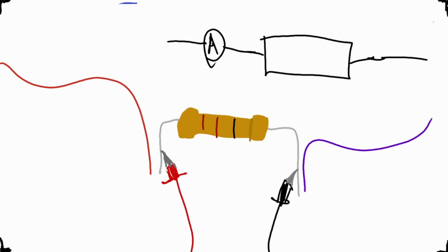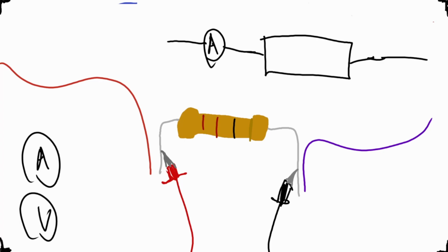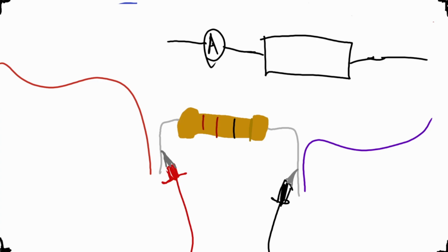Also, when I use the symbol A for ammeter and V for voltmeter, these are circuit symbols for talking about measuring the voltage and the amperage in a circuit. In actuality, it is the same multimeter. It's not like they're different components. It's just that when you're measuring voltage, your multimeter's dial will be selected towards the voltage section, and when you're measuring current, you change the dial so that it's on the appropriate current section. That's all it means in actual physical terms of using the multimeter.